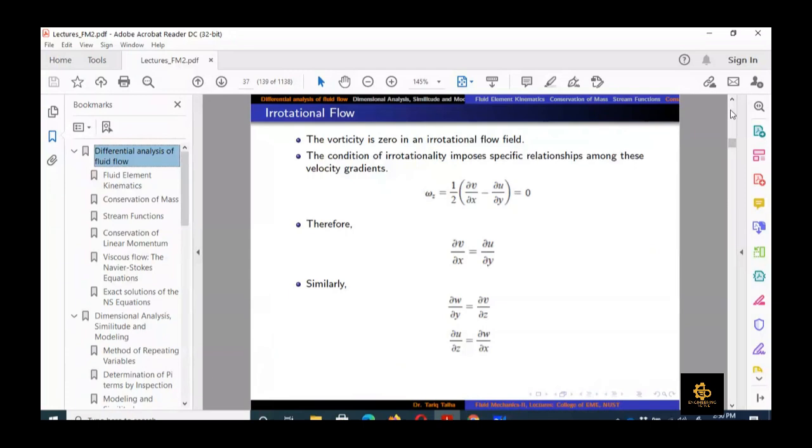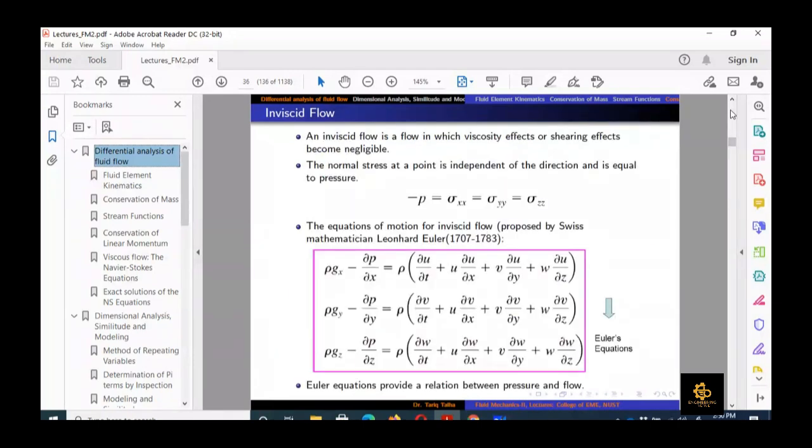So we derived the relation in the last class for the inviscid flow, in which there is only normal stress, which is pressure. In non-viscous fluid, there is no shear stress. So we have only normal stress, which is pressure in that case. And we know from our hydrostatic knowledge of chapter number 2 that pressure is a compressive force. That's why we use a minus sign for that.